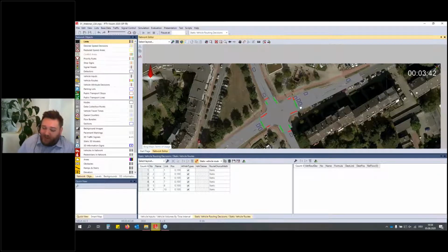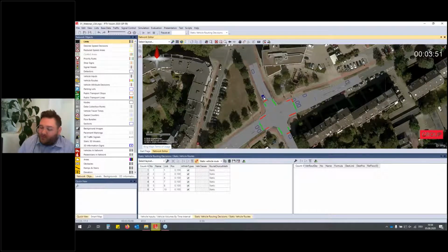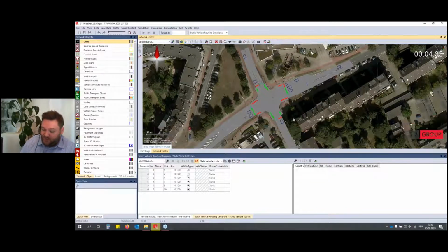If we, for example, select now this detector here and set a single activation, the traffic signal should switch to the state where these roads with minor priority receive a green signal, and we can set a single activation just by double-clicking on the detector. Like we see now, the control does exactly what it should do and changes now back to our ground state where the roads with major priority receive a green signal.